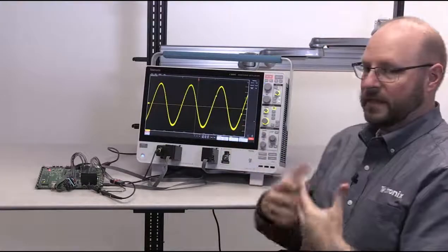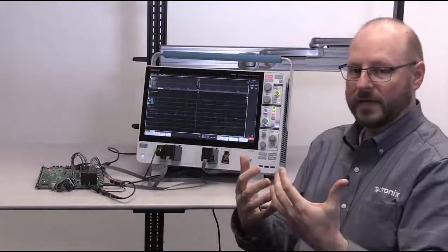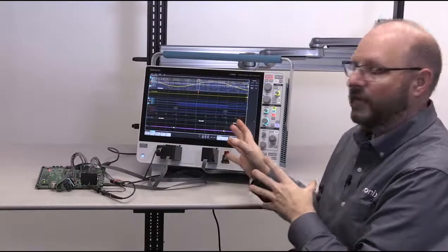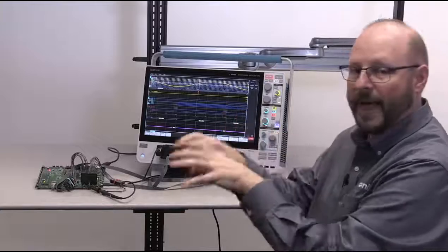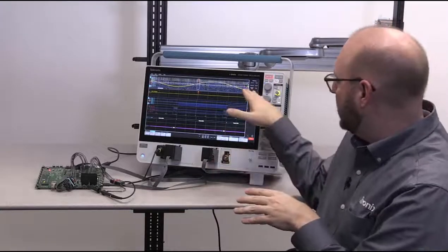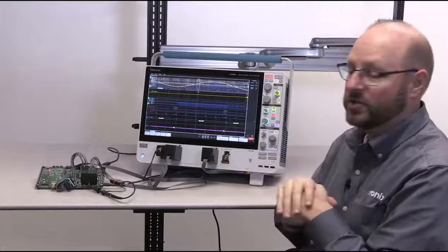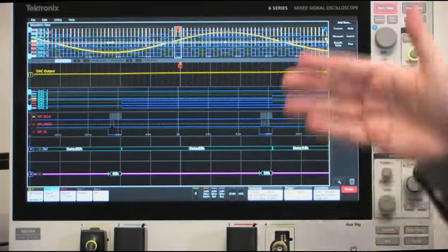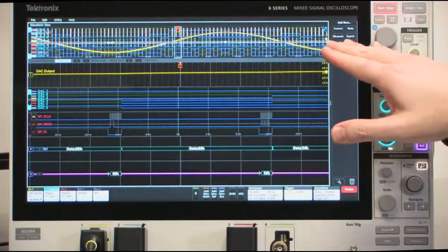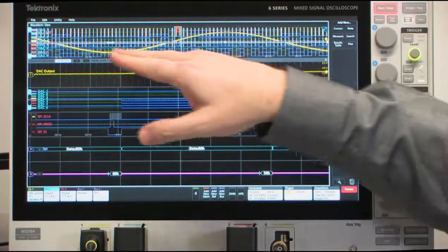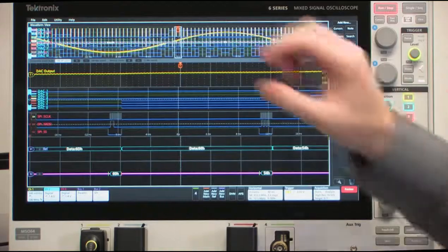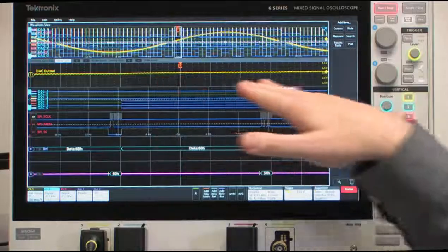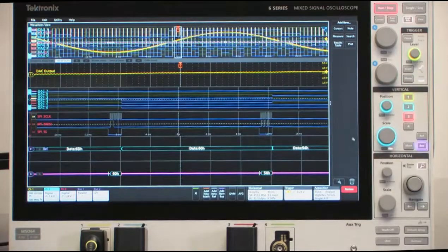What you'll see is that the actual setup of the oscilloscope will be done, and there'll be real data that was acquired when the session file was saved. This data gets put back into the acquisition data. That's why you see the output of that D to A converter showing up on channel 1 rather than a reference file. In this particular input, you can see in the upper section of the overview the actual sine wave. We're zoomed in on a very narrow portion of this, so the sine wave actually looks like a standard single value voltage output here.